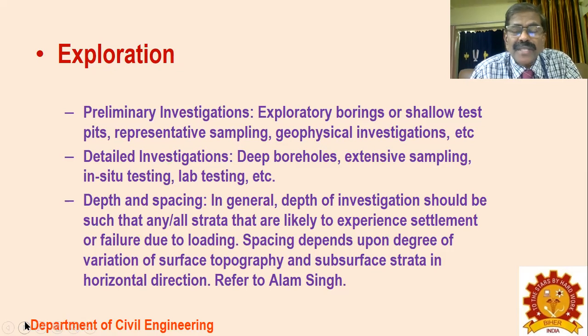Depth and spacing. In general, the depth of investigation should be such that any or all strata that are likely to experience settlement or failure due to loading are covered. Spacing depends upon the degree of variation of the surface topography and subsurface strata in the horizontal directions. This was given by Alam Singh, a great Indian author on soil mechanics. So it is a fair judgment of the great authors. The spacing depends upon the degree of variation, things like that.